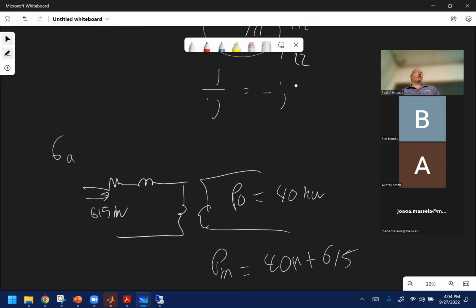We do that a lot in the real world because we want to see how efficient our system is, and it's becoming more and more important because we have EV charging. The efficiency of the grid has to be included in the calculations of whether EVs are the end all be all for cleaning up greenhouse gas emissions. They're not perfect. They have a lot more line losses on your system, because you're putting more power on the grid. So line losses are going to increase. So not perfect.